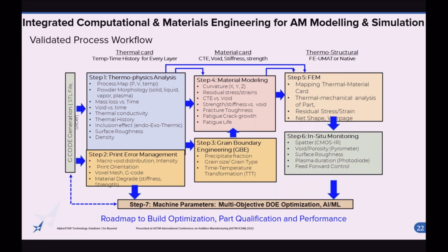There are single criteria and multi-criteria methodologies built into the system, baseline AI and machine learning tools, as well as the capability for a user to add in any specific subroutine they think would be necessary to look at the data and assess patterns to identify the ideal process parameter settings to ultimately mitigate anomalies that may arise as a result of the build plan or the fabrication process. And with those optimized process parameters, mitigate, eliminate those defects, anomalies, and the effect of those defects.